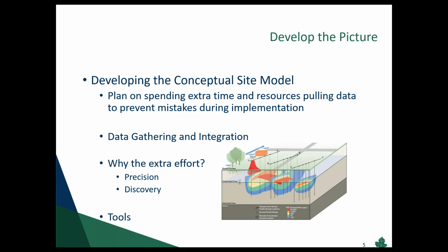Okay, so what are the pros and cons? I would imagine that the soil borings are going to add more time. The soil borings will be more time, quite a bit lower on the day rate cost, with a little bit less production. The biggest con is that the soil samples generally need to go off-site for laboratory analysis, and you've got a pretty good delay. You can bring a mobile lab on maybe for groundwater, but you still are going to have a lag, right?